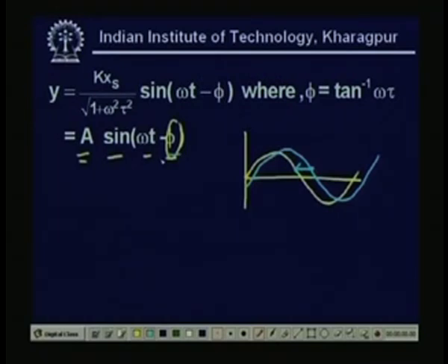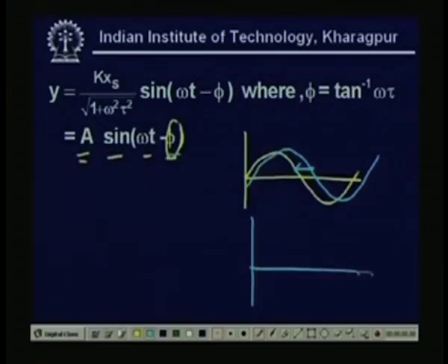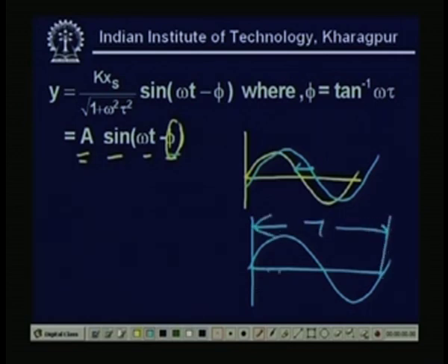Even though the circuit is very simple, with one resistance or one capacitance, I can make a lead lag network, right. So, this is my output, you can see here. So, the phase change is coming, and as I told you earlier, this omega is very important in the case of sinusoidal signal. That means, omega equal to 2 pi f. What is omega? If I draw it here again, if my input signal is like that, this is my total time period T. So, f equal to 1 by T and 2 pi f equal to circular frequency omega.